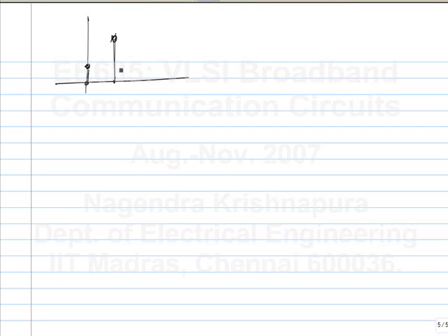Let's say we make a DFE for this. Now this, normally I think of as a precursor ISI. Okay. So I say that I can't use a DFE. But you can equally well say that this is my cursor, right? That's a completely arbitrary distinction. I will say that this is the cursor and I'll cancel this off. What will be the problem?